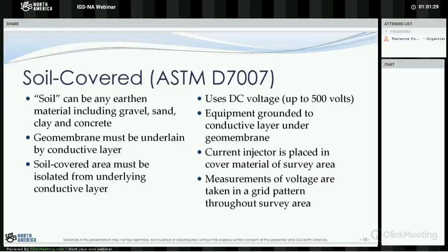If there's an access road in place that they use to place material, it will follow the access road. It simulates a leak the size of the cross section of the access road. So it's not going to go through a 1/4 inch leak in the liner when it can go through that access road.